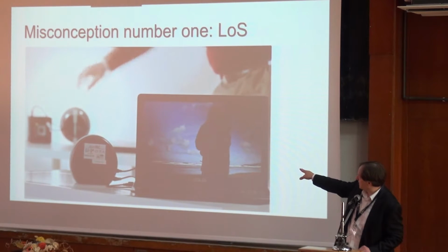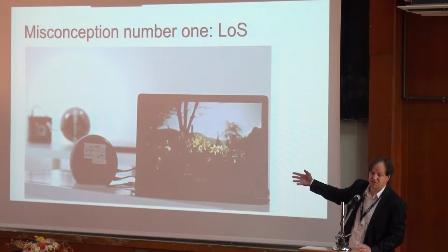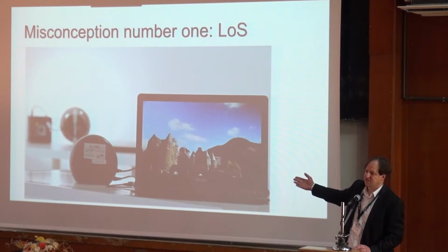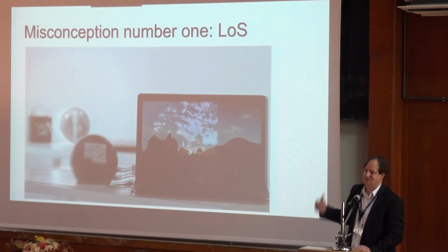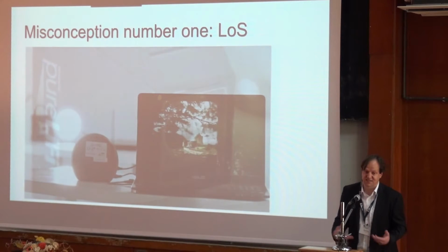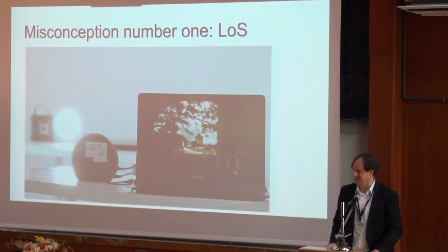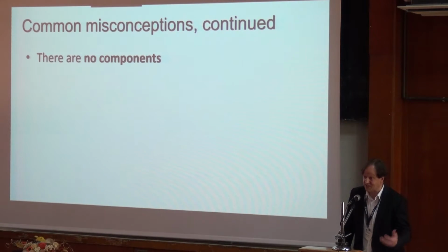The video stops slightly. This is adaptive modulation coding kicking in. But now the video resumes with a lower order modulation scheme in place. But it is still transmitting data, although there's no direct pointing into the receiver in that case. So it's basically working now in a non-line of sight scenario, only from the reflection. So it's working like any other communication system.